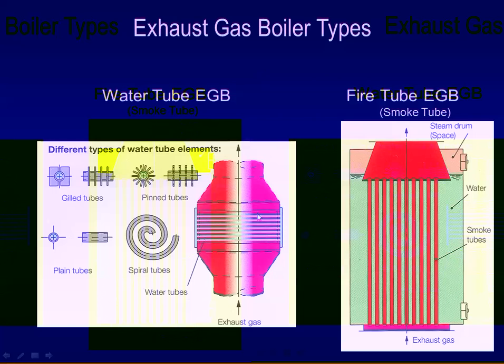But specifically on this, watch your circ pump discharge. If you see that pressure drop very suddenly, the tubes have been holed, and you're worried now that you have a metal fire. You have to shut down the circ pump, and you have to shut the inlet and outlet return from this system, because now you're worried about pumping water to a metal fire. It will break down the H2O into H and O2, and you're feeding hydrogen and oxygen to that fire. Absolute worst case scenario.